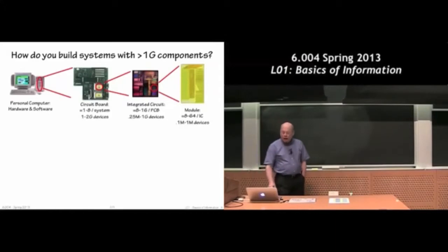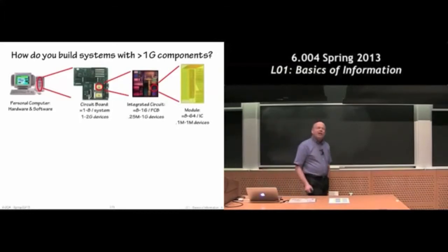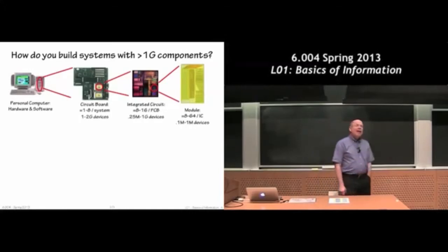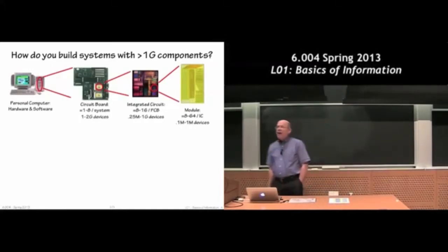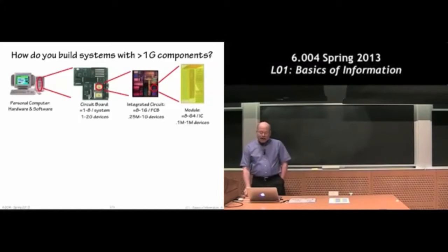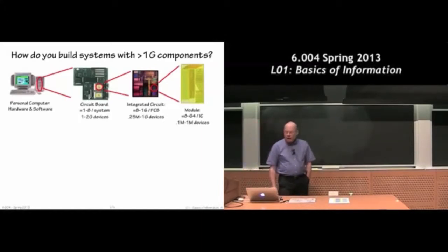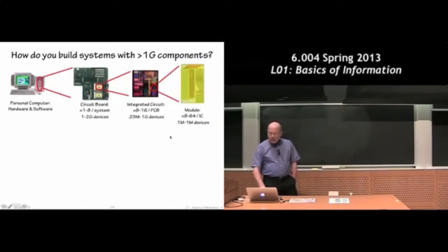If I zoom in on one little piece, one of the CPU cores inside your die, which contains many things besides just a central processing unit, memory interfaces and cache memory and graphics units, lots of things inside here, we might see something that looked like this. I'm beginning to see a little bit of fine structure. I can get a sense that maybe those stripes across the top are actually a 32-bit bus connecting, in this case, a very deep register file to the data path of the CPU.